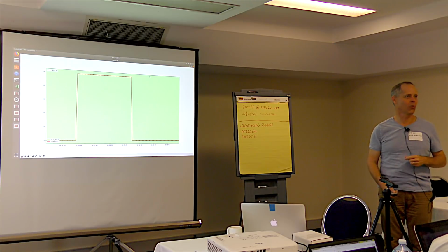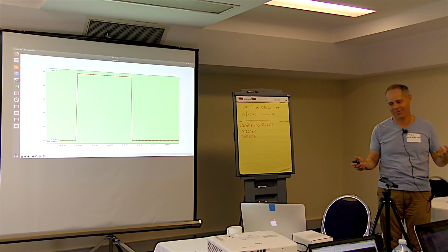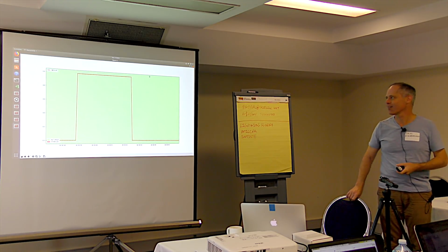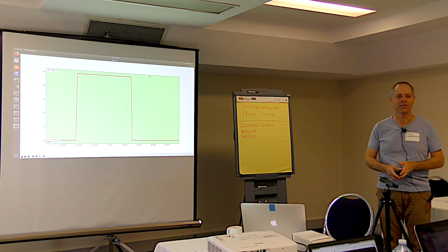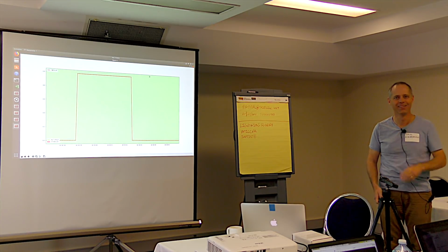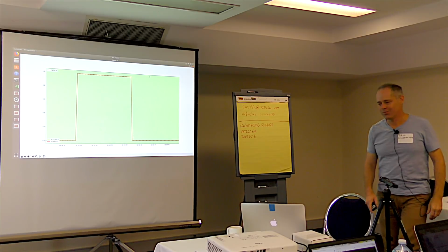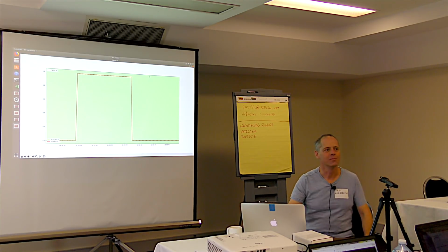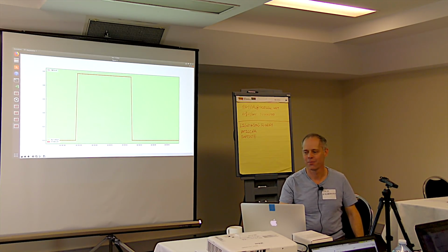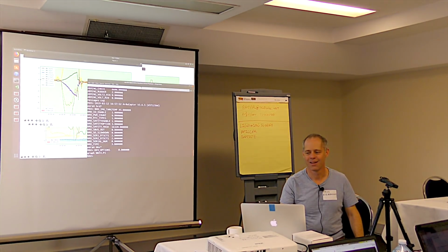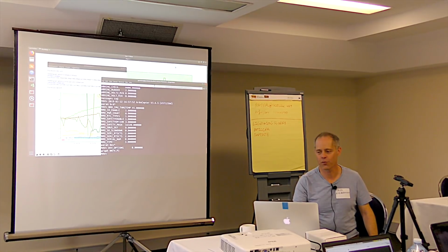And the question was, well, why did it select the wrong EKF? It selected the one that was momentarily healthy. So that's got to be a pretty odd one, to run with your IMU actually upside down. I mean, that's a pretty serious hardware fault. That is a serious hardware fault.